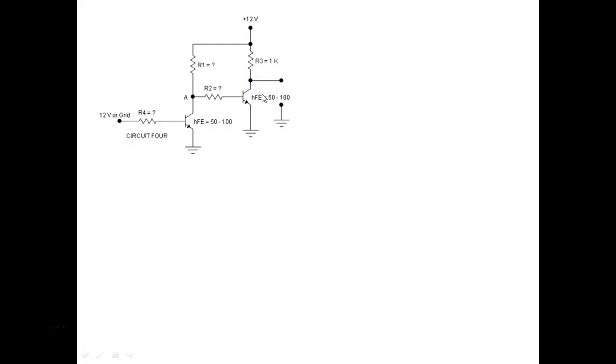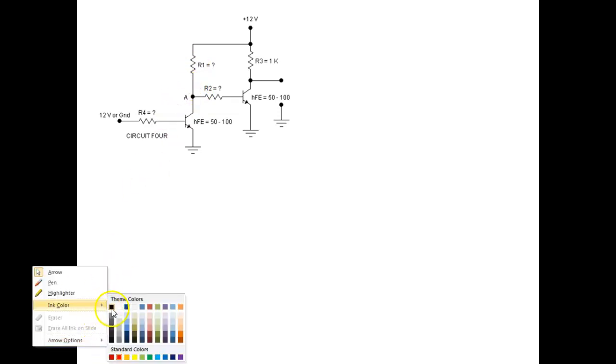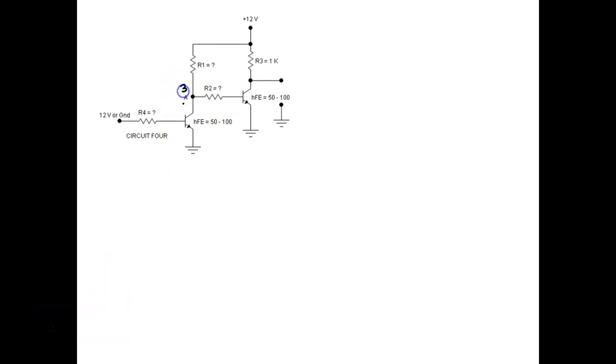So that means to turn this transistor saturated, we've got to have a voltage at point A. So we established, and this is what you would do if you were going to design it, 3 volts. We know we've got to have more than 7/10, right? And we've got to have enough where we can control it, so this resistor will drop a voltage. So how do I get 3 volts right there?